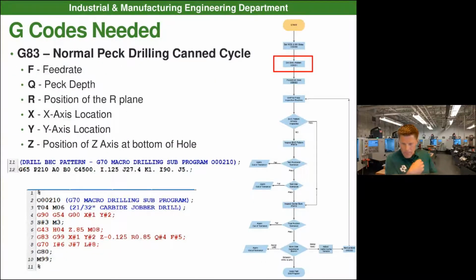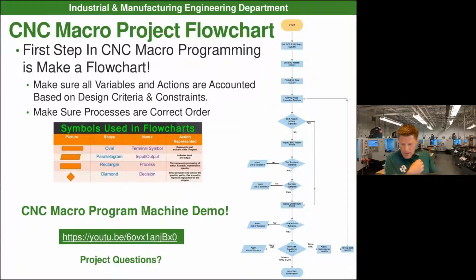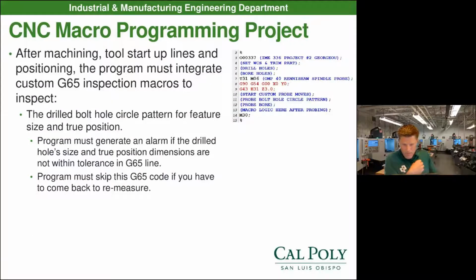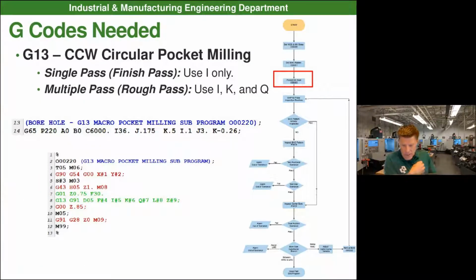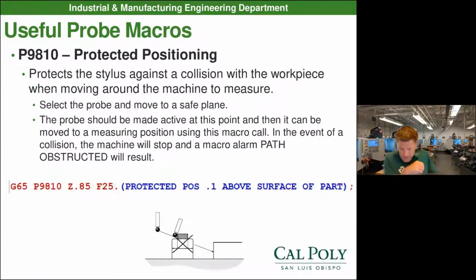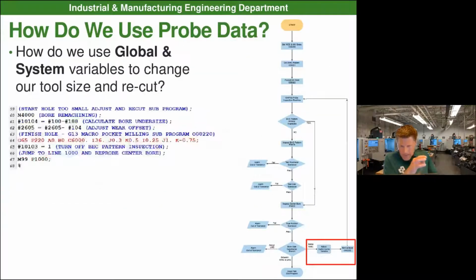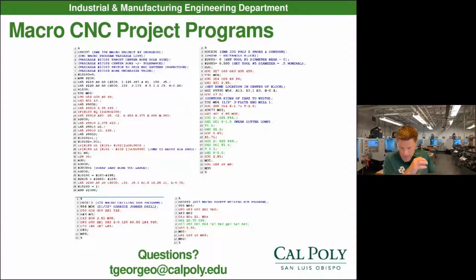So moving up, you can see when I go to probe, let me go all the way to the back. You're going to see I put in the G65 and that P line, and it's hard to see, but you'll see I have an H and an M. I can't mark it up right now, but in that G65 line, there's an H value and an M. I added those externally to check that true position or that actual size.